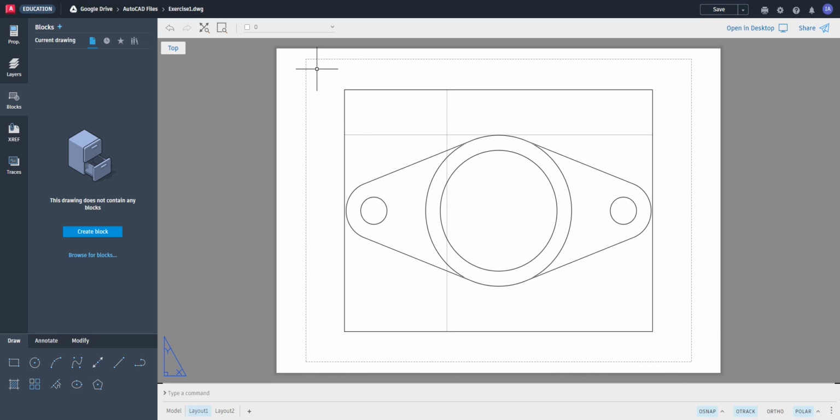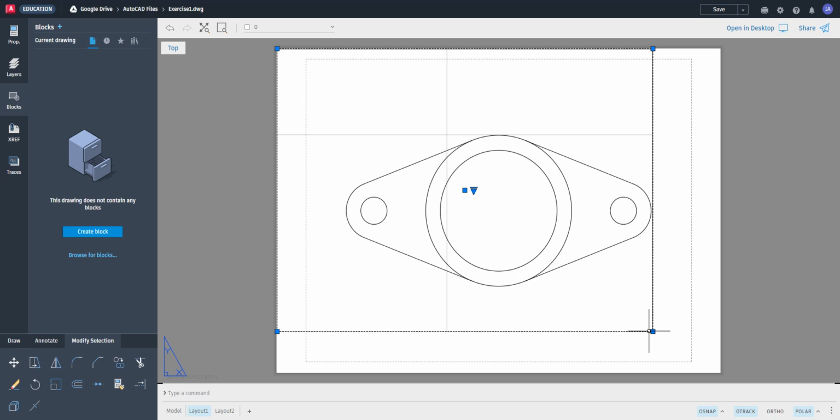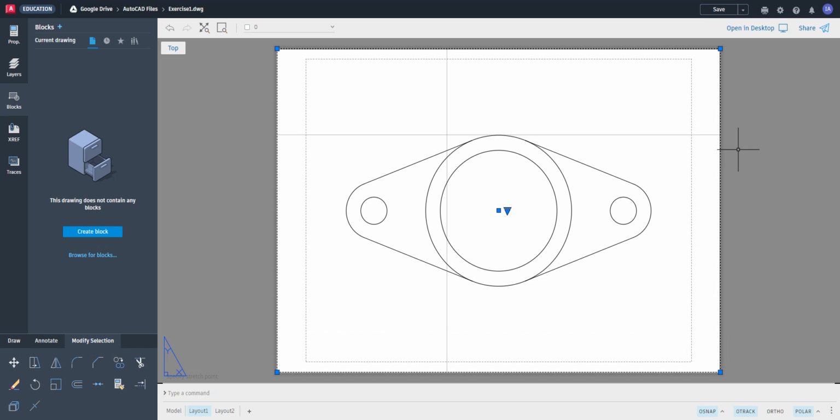That's your margins. What we're going to do first is we're going to move this, click on the viewport, and we're going to move this corner, okay, all the way to this outer corner here. And we're going to move this lower corner also all the way out to the edge of the paper as best as you can. All right. Since it's outside the margin, that rectangle around it will not be printed.